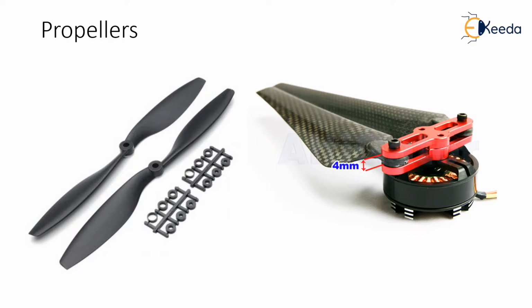The drone itself uses multiple propellers in pairs to create a balance. You have likely noticed that some rotate clockwise and others rotate counterclockwise. This is to help keep the drone itself from spinning out beneath the props. As a propeller spins, the force applied by the motor spins the propellers as much as it tries to spin the drone. The opposite side motor spinning the other direction creates a balance, preventing the drone from spinning so that most of that energy goes into the propellers. More about the propellers will be covered at a later part during the course.